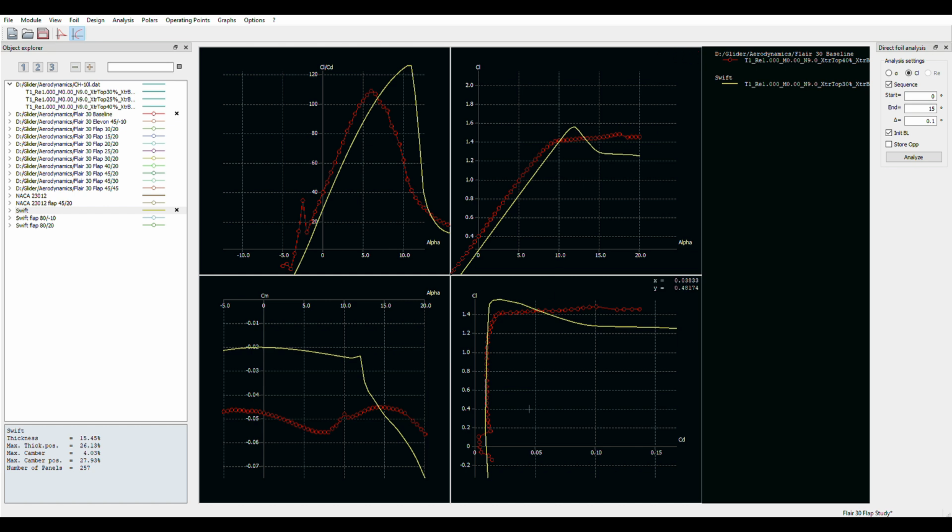And down here is really impressive, the drag bucket. Flat drag here over the full spectrum of angles of attack, even slightly negative. And it's all the same drag as you go up in CL. So you're gaining lift, but the drag's not going up, which means that your L over D is improving. As you go closer to stall, you're getting a better L over D, which is great because as you go slower and slower, you're probably heading towards thermaling or light lift conditions, and you want more L over D, and that's exactly what this airfoil does.